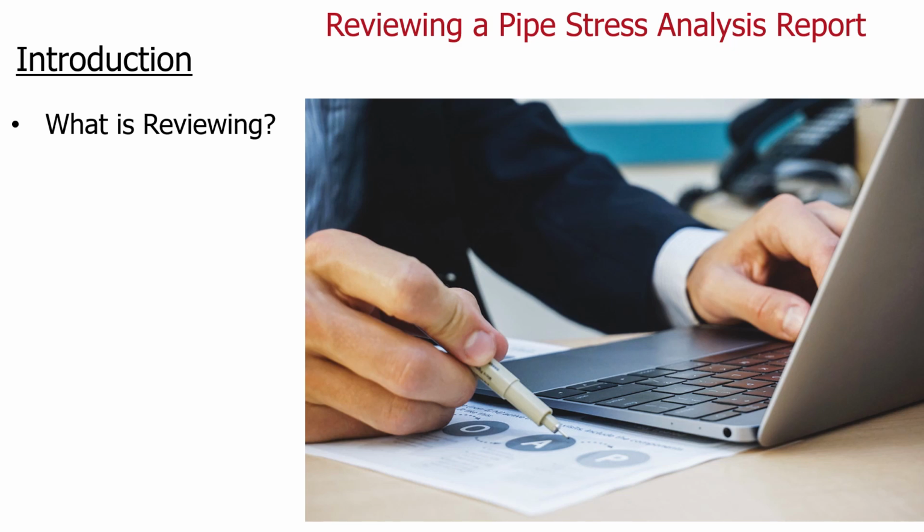You already know that a piping system has various conditions of operation. Even the code tells us to check various stresses like sustained stress, expansion stress, and hydrostatic stress case. All those stress cases we have to check in the system, whether they have been performed or not, or whether the report shows them as considered or not, and then we have to verify.